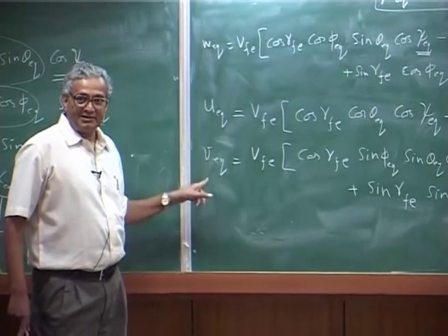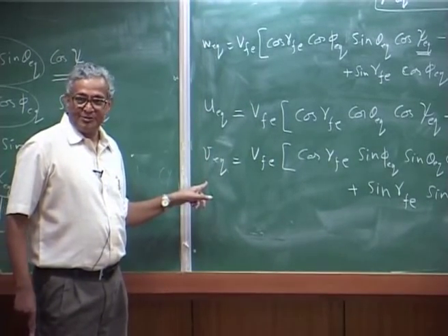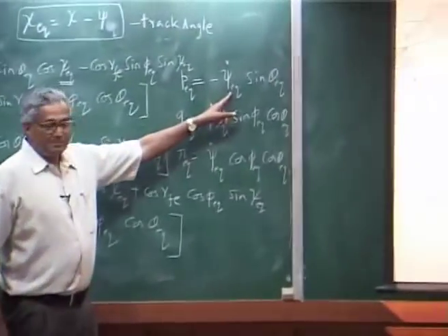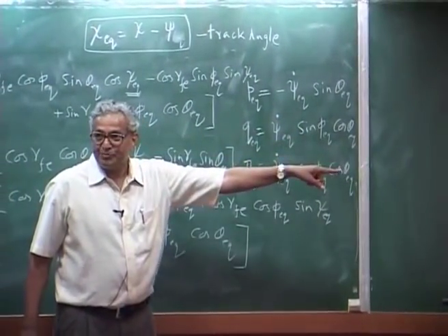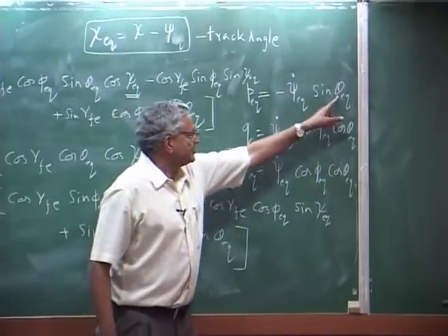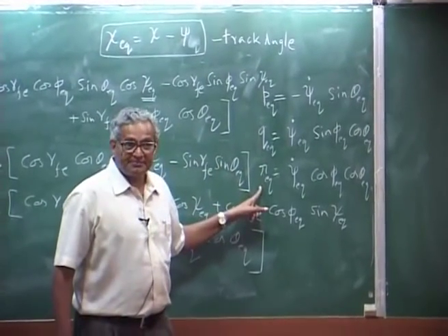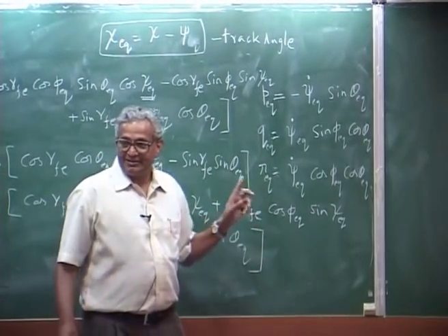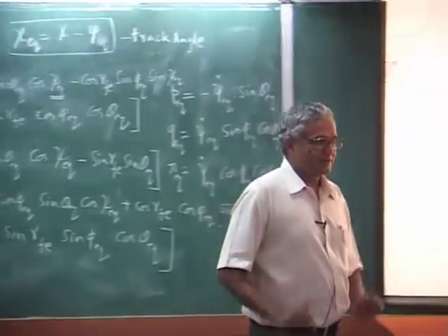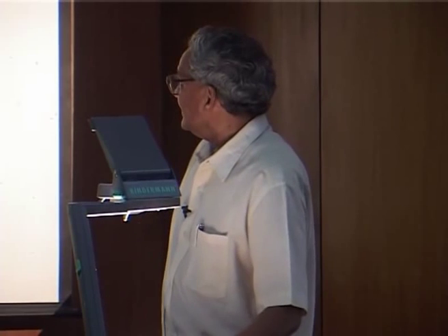That means, you have all the 3 quantities, okay, and given psi dot, that is the input equilibrium turn rate. You have already assumed theta EQ, PEQ. That means, I know PE, QE, RE. Okay. You go back to the 6 equations and then solve. I will just briefly mention, because this procedure is quite complicated, that is where the convergence comes in. See here I briefly describe the procedure that is done. Trim procedure I just put it complex.